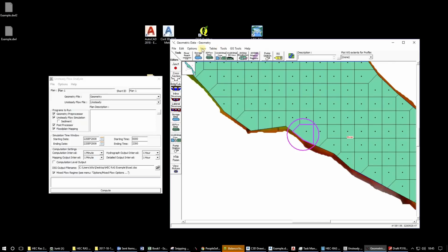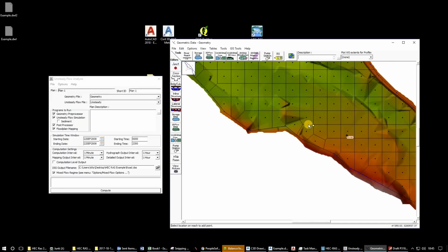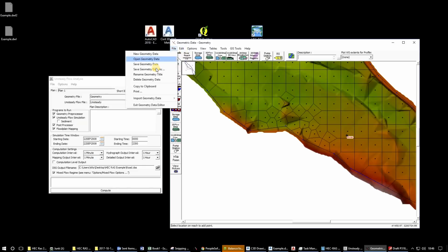Okay, so it doesn't like that little portion. Let's add a bunch of points in the vicinity, basically refining the mesh. I'm doing it very, very crude now, so it is definitely not ideal, and I don't like this big mesh, but it should still produce relatively accurate answers. The mesh really doesn't have to be that small like we did initially.